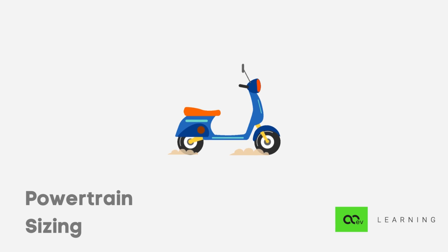In case of a two-wheeler like a scooter, we find ourselves with motors of 2 to 10 kilowatt of power. Now for these kinds of motor, the voltage can be of any value. We can even have voltage of 400 volt, and when we divide the power by the voltage, we find the current in the range from 5 to 25 amperes.